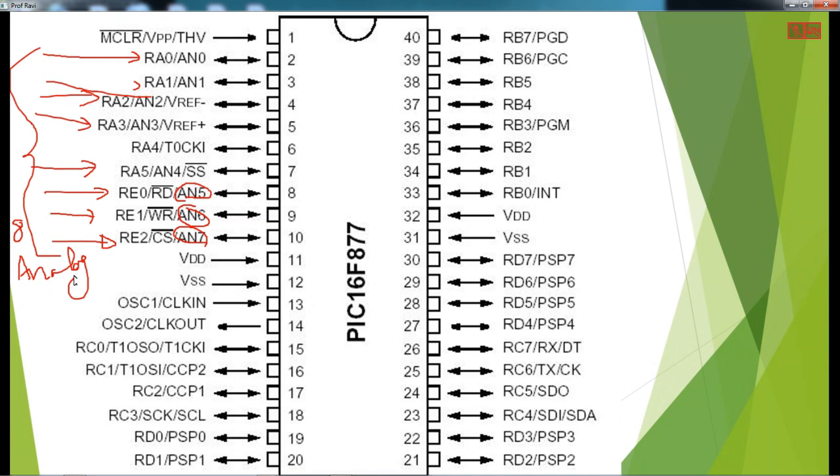All right. Now let us see, when you are trying to connect the I/O devices to the PIC microcontroller, how can we configure or initialize these particular ports? As we discussed up to now, if a port is acting like an input port, then it should have a buffer. And if any port pin has to act like an output port, then it should have a latch.